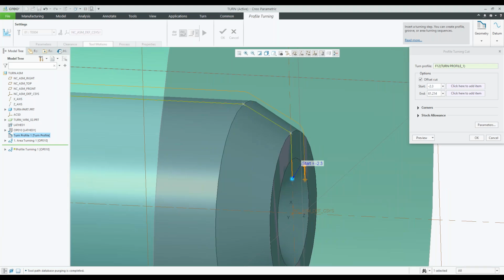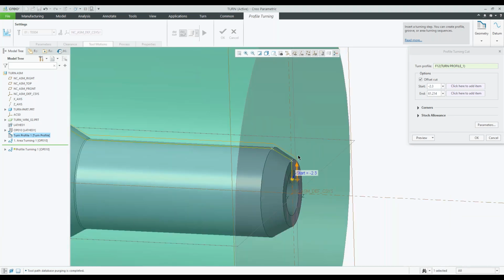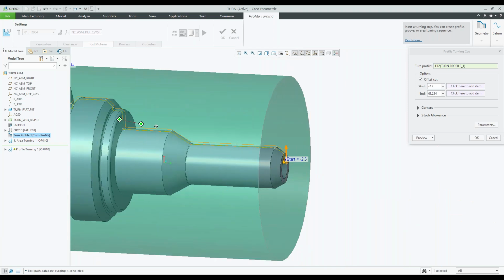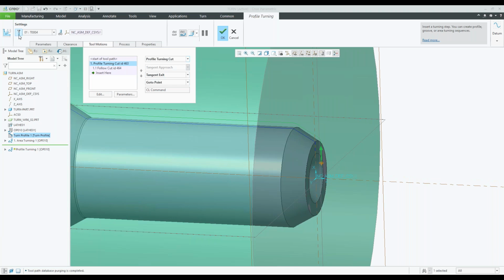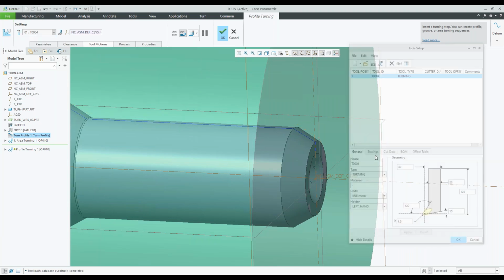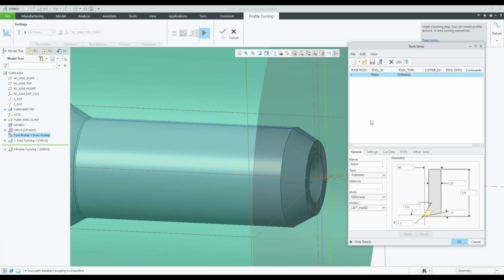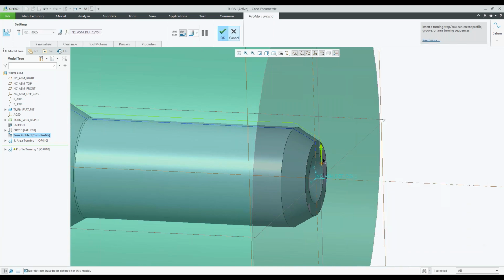So that's going to finish my outer profile, and then I'll come in with a drill or maybe a different tool, or maybe my finishing tool is different. The tool 5, maybe that increased to 20, 35 degrees, whatever the case might be. So it's a new turning tool, and I'm using that now to finish my part.